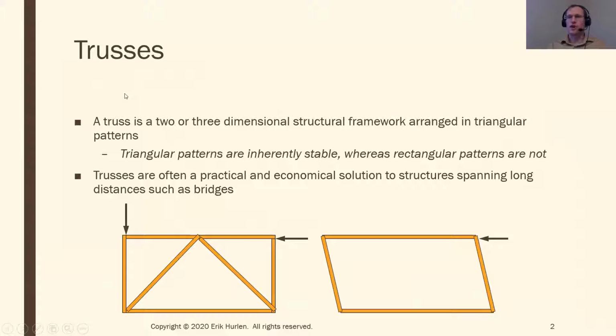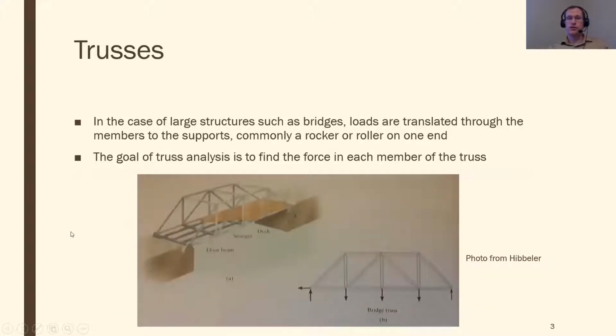But first of all, I'm going to describe what we're actually doing here. Usually when we do these methods of joints or method of sections, we're looking at some sort of big structure. So something to hold up a whole lot of weight, something like a bridge or a roof. And those are usually made out of these kind of triangular patterns. If you ever crawled up your attic or looked at a bridge, usually have some triangles involved. The reason for that is because a lot of times we can assume any connection is a pin connection. So anything that's connected will allow some rotation. So if you're going to allow some rotation and you come along and push on it, this thing without triangles is just going to start to fall over, and that's not a good thing. So the triangles stop that from happening. So that's why I usually see triangular patterns in these big structures, like these bridges.